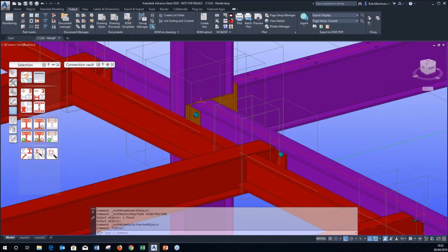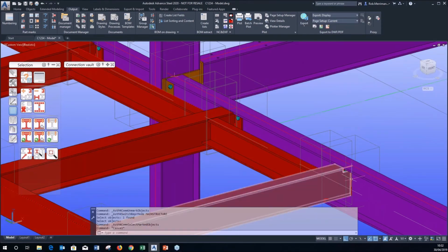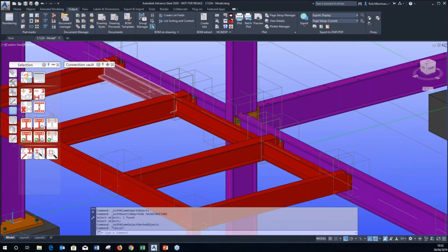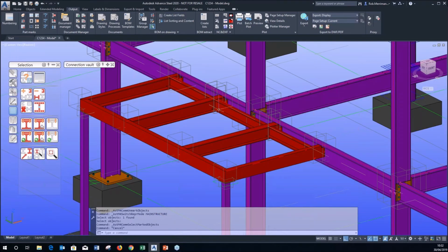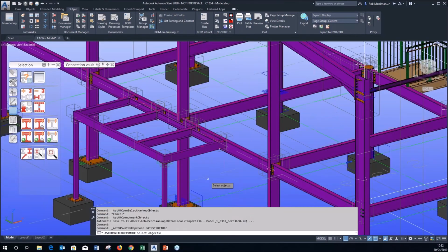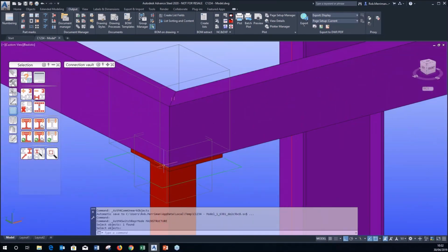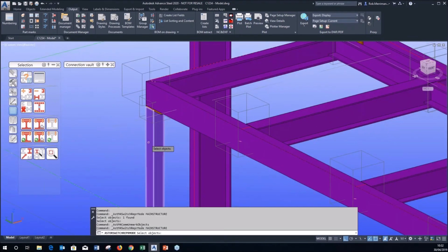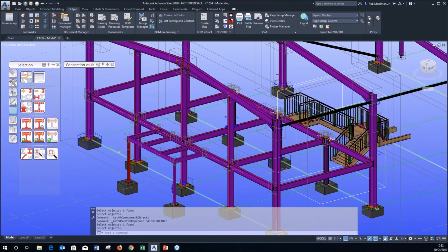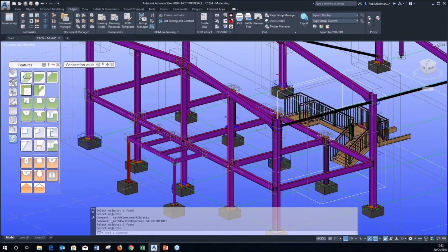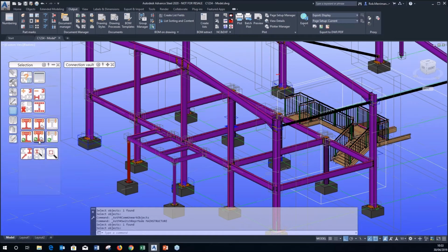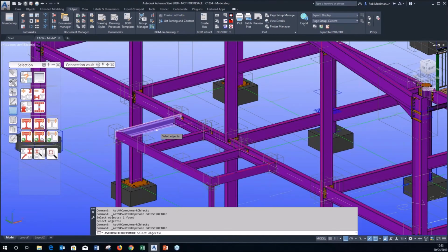So we can see all the end plates go red. And more importantly, all of these trimmer beams have now gone red. So this is now welded, and everything on there will show on the assembly drawings. And I can do the same in here just to double check those cap plates are welded correctly. Now what I would do is, if you're using any of the functions in here, I would always use this clear marking and display objects connected in shop. Again, like the clash checks, I would never leave any of this to the end. Once you finish modeling this balcony frame, I would do a quick check of what's attached in the shop.